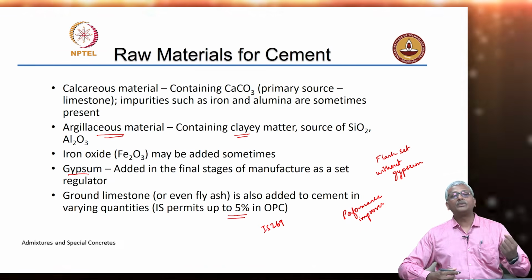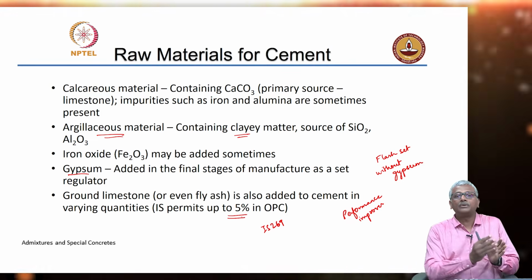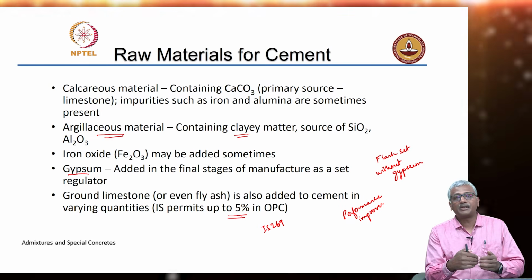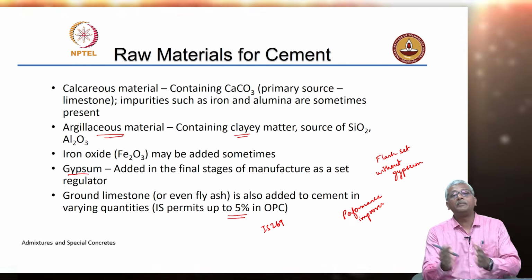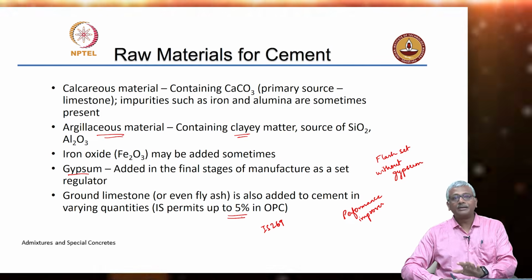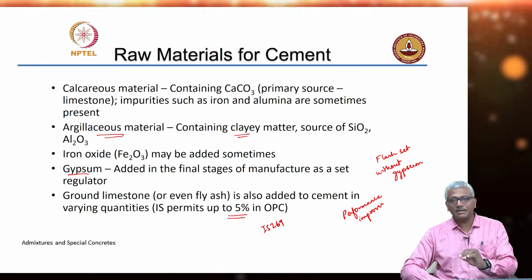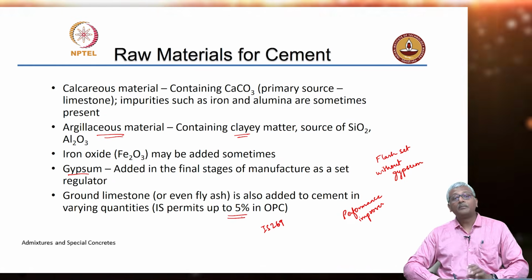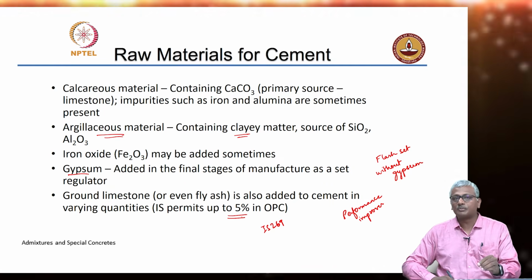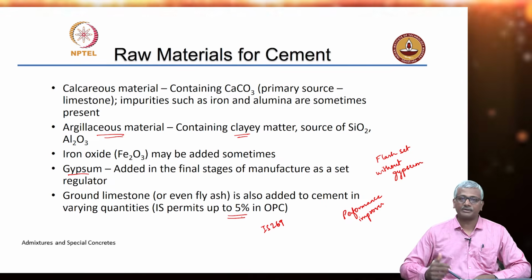One is that you're cutting down the extent of cement clinker that is present in cement by 5%. That means directly you have cut down the amount of material that is produced through the burning process, which evolves CO2. Here, this material is just added while grinding, so you're not liberating additional CO2 from this 5% material. So, performance is generally improved in terms of the sustainability impact of the cement. So, this 5% is a very key component of cement characteristics, but you will learn later when we talk about mineral additives that this limestone that is added as a performance improver can to some extent also lead to additional benefits in terms of the chemistry of the cement itself.